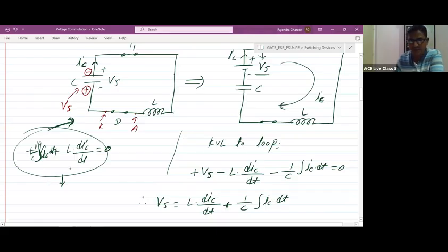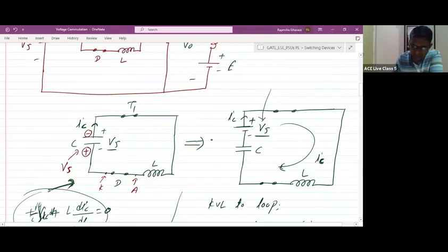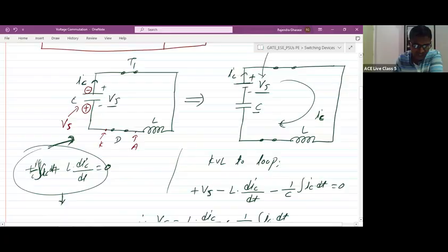So in order to avoid this, because that is somewhat confusing, what I did is I have added the initial voltage of the capacitor here, and I have considered the capacitor as passive. We are having the initial voltage across the capacitor, and at the same time the capacitor is passive also. These two things I have separated here.